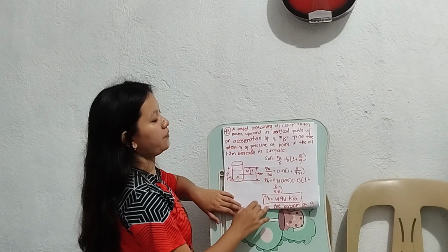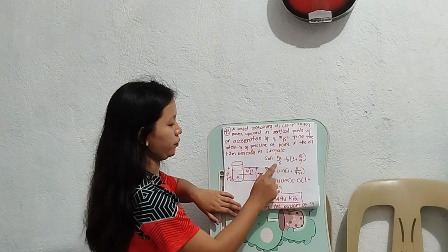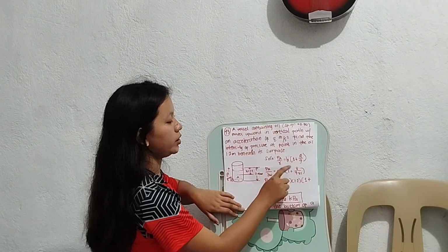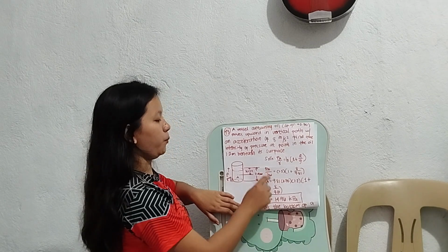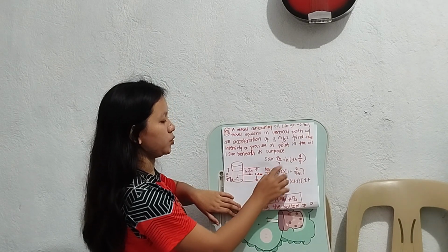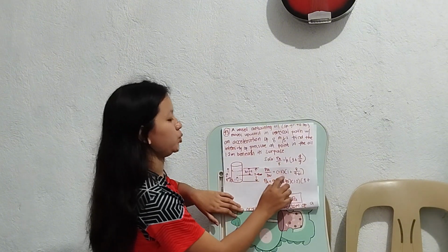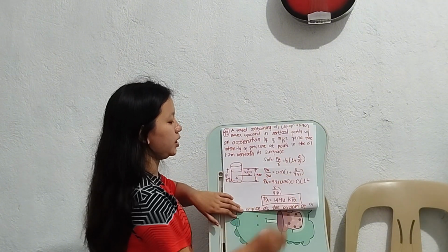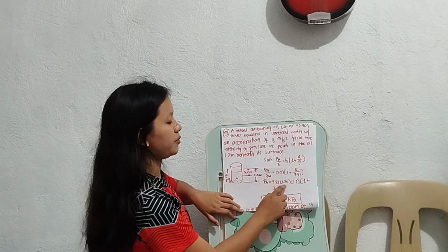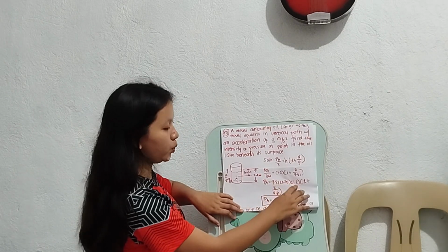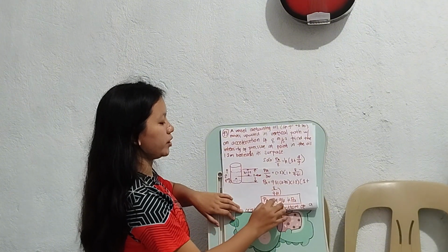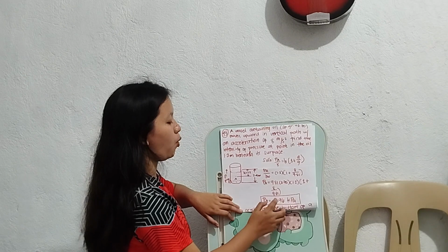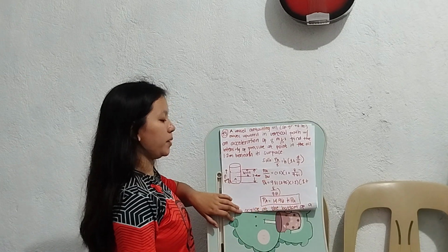So we have a formula here. Pressure head over unit weight is equals to H times 1 plus A over G, or the gravity. So P over unit weight equals, which the H is 1.2 times 1 plus, which is the A is 8 over 9.81 gravity. So 9.81 times 0.70 times 1.2 times 1 plus 8 over 9.81. So we came up with the answer of P equals to 14.96 kilopascal.